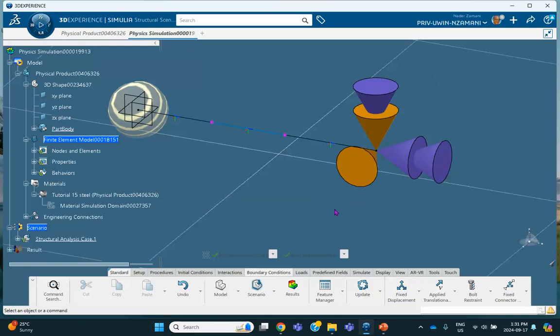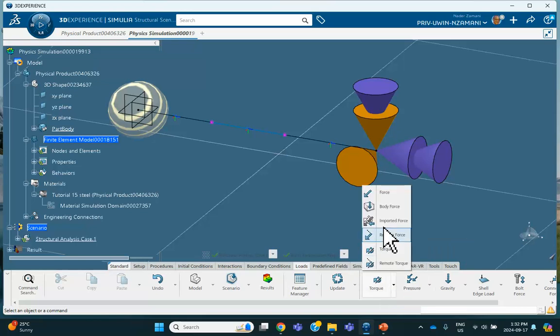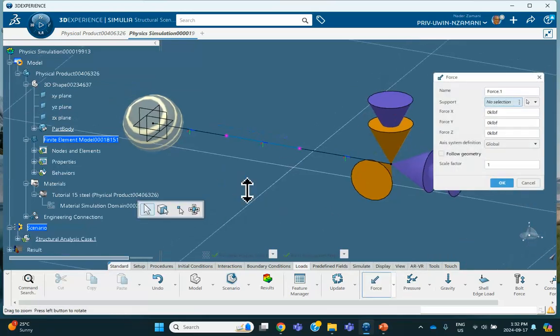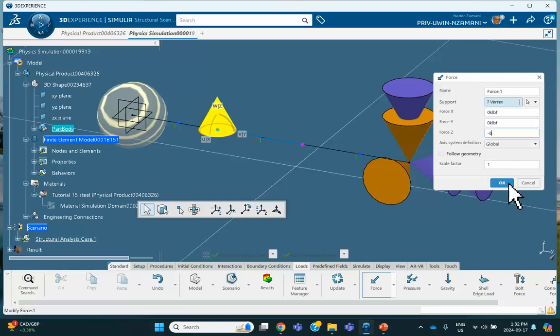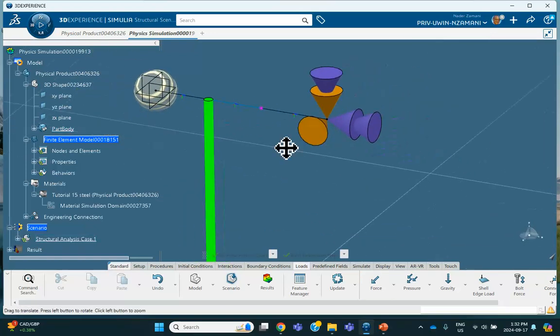For the load, so we go to load. Let's do the force first. At this first point, these are tied together, meaning that we're going to select that vertex, and if it doesn't work, we're going to create a group for node and put a node in it and then apply it there. I think this should work. So -8. Yeah, and then a concentrated moment at this end.